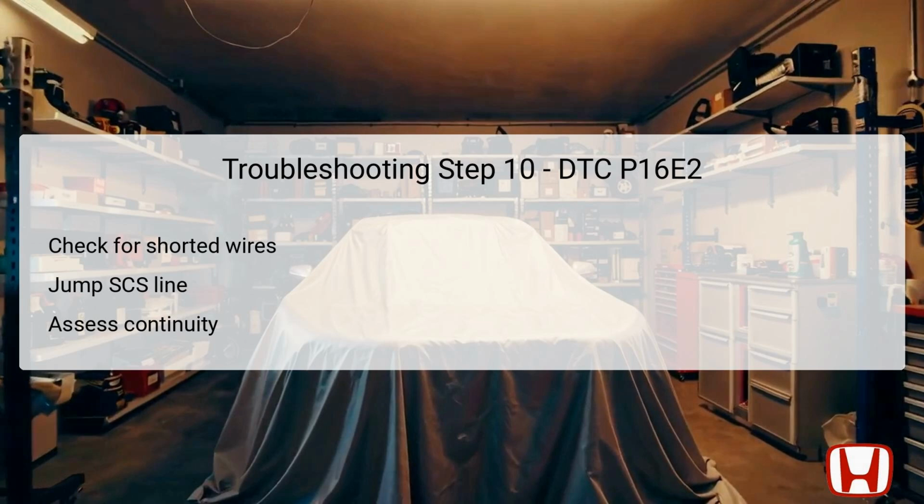If checking continuity reveals a break when one of the connectors is disconnected, it confirms that the wire is intact. If continuity fails throughout, more extensive diagnostics will be required to pinpoint and repair short-circuit locations in the LIN circuit.